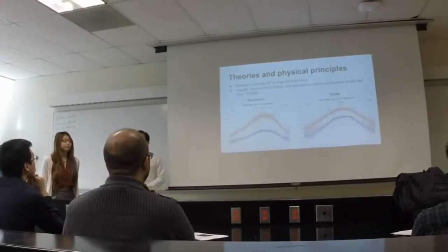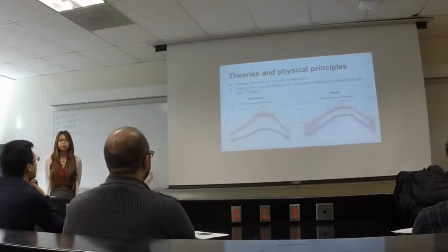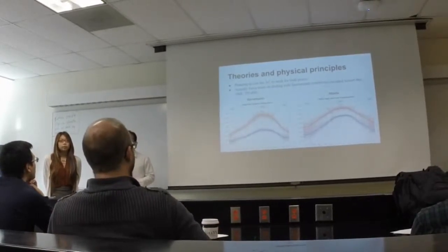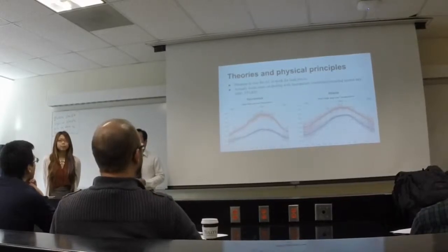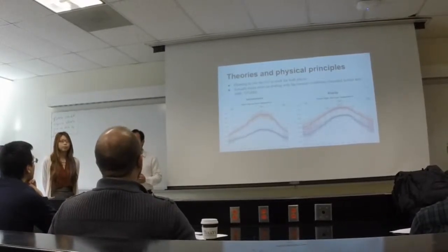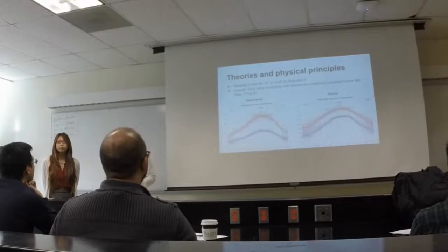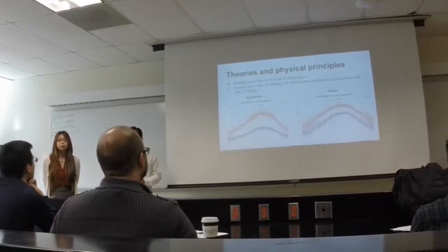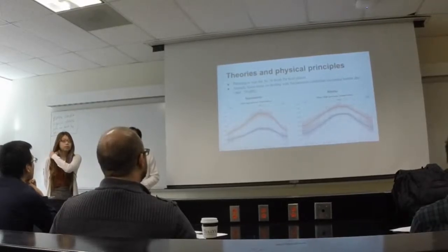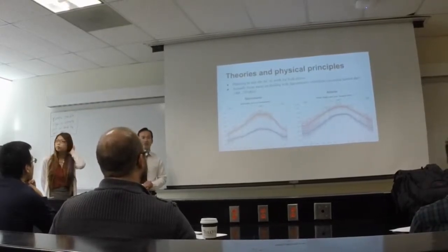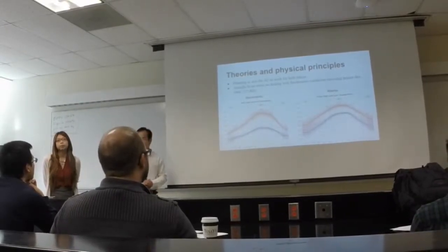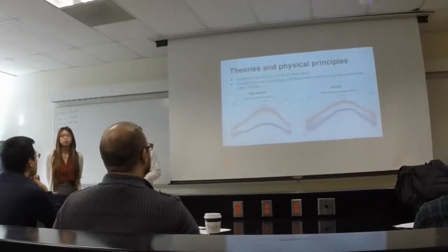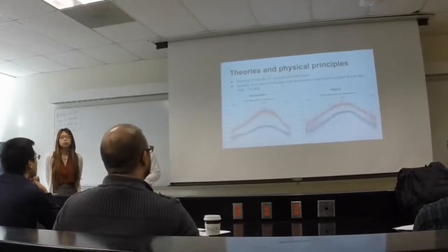And we need to size the AC unit for both places. The first place is Sacramento, which is hot and dry, and the second is Atlanta, which is a little bit less hot and more humid. Because Sacramento has the hottest record, going up to 106 and 73 relative humidity, we're going to size the AC unit especially for Sacramento. But the dehumidifier will take care of the Atlanta case too.